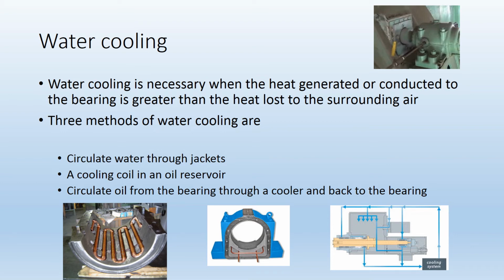So there's 3 methods of water cooling, and those 3 are circulating water through jackets that are inside the bearing, installing a cooling coil directly in the oil reservoir of a bearing to help take the heat out of the lubricant directly, and the third is to have an oil circulating system, so oil is circulated through bearings, and the heated oil that's coming out of the bearing will then go through a heat exchanger and then circulated back in.